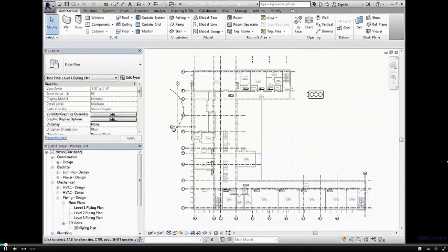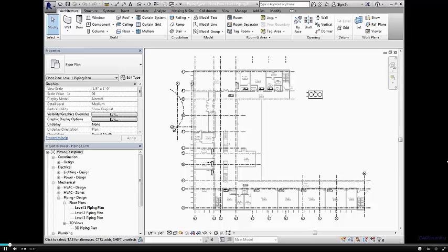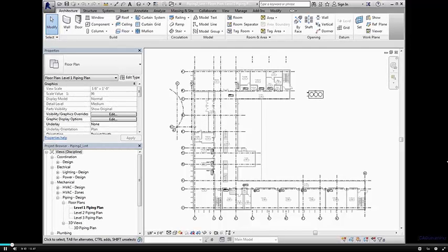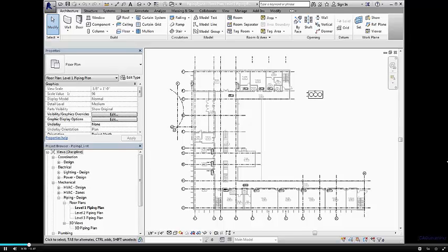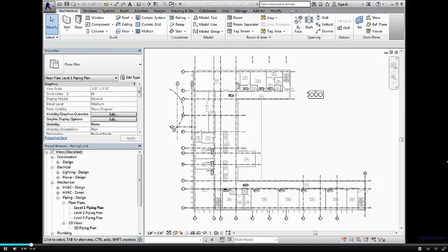Piping systems can be created in two ways. One way is to add pipe to connect the waterside components, and they will automatically be added to a piping system. The other way is to select the components and manually add them to a system. Then you can have Revit generate and lay out the piping. However, with several components in a system, it is difficult to get the results you are looking for. In this model, two piping systems have already been created: condenser water supply and condenser water return.